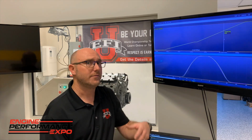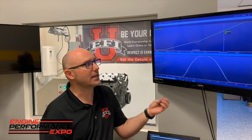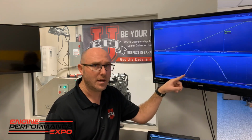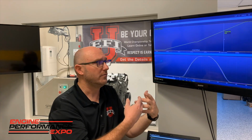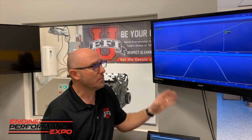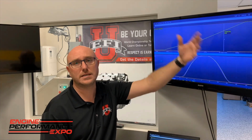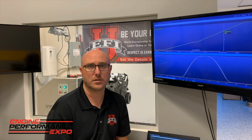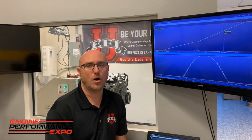Think about it. If the valve motion, which is our supply side, is not keeping up with the demand side because the valve isn't actually following the commands that the camshaft is giving it, whether that's from flexing, whether that's from the valve spring not having enough force, or maybe it comes all the way up and it comes all the way down and closes, and then it bounces off the seat again and goes open simply because we didn't have enough valve spring pressure to keep it closed. When that happens, the performance will always suffer.